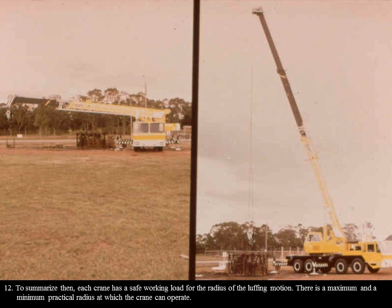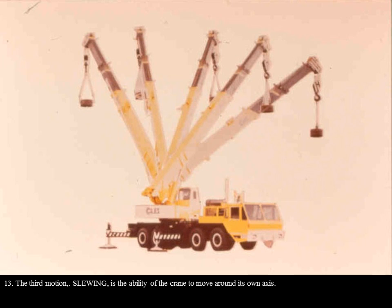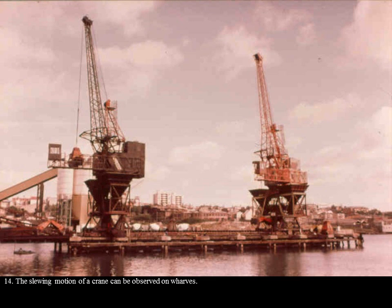To summarize then, each crane has a safe working load for the radius of the luffing motion. There is a maximum and a minimum practical radius at which the crane can operate. The third motion, slewing, is the ability of the crane to move around its own axis.